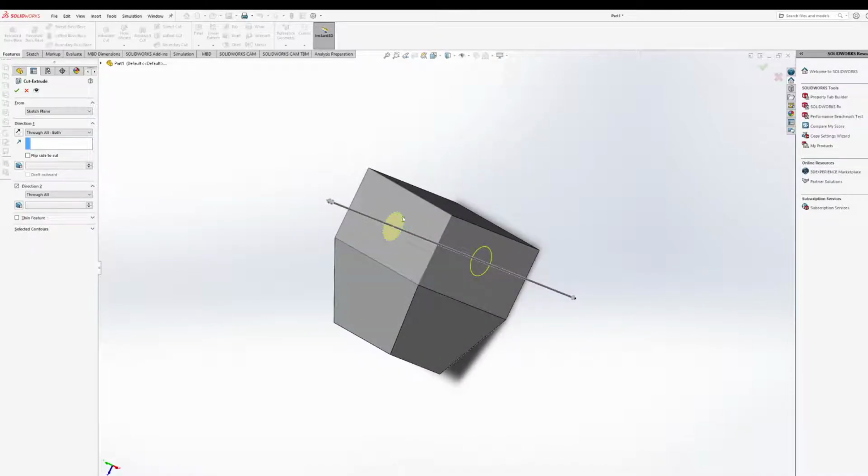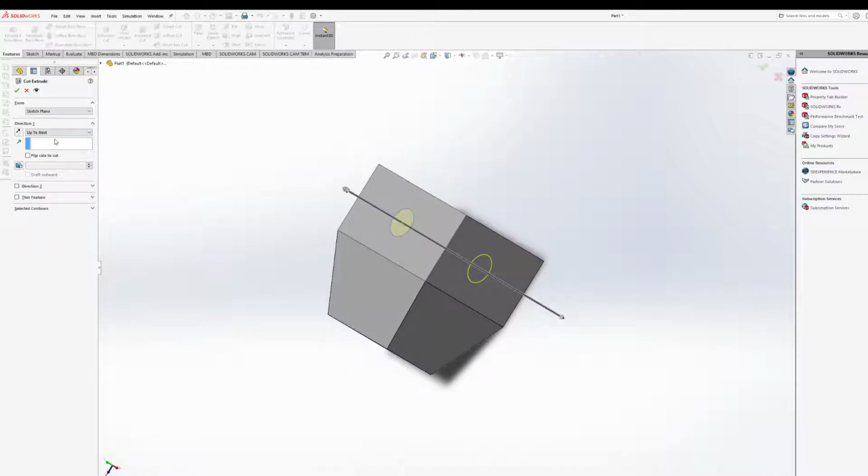So if there is some other thing, or rather, let's say you're not starting this sketch out on a surface. Let's say you're doing it inside of some sort of shape, and you need to create this hole on both sides of your sketch plane. So this is kind of like the two dimension. As we can see, it already selected the direction 2. But if we click off of it, I believe it gets rid of it. Yeah, or I could just get rid of it like right there.